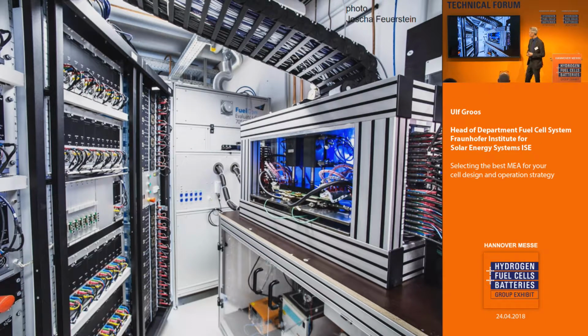This is done in such a way that we integrate the along-the-channel test cell into this measurement setup. We contact each segment, which gives a lot of cables, because for each segment, anode and cathode, power line and sense line, so 4 cables per segment with 25 segments. You have a lot of cables. Each segment is connected to a single potentiostat.